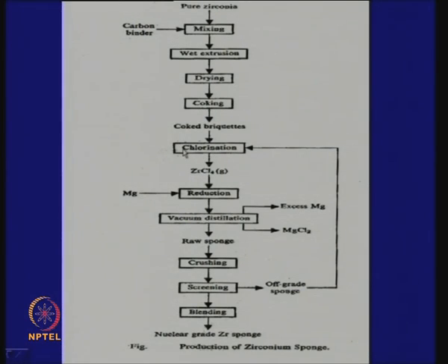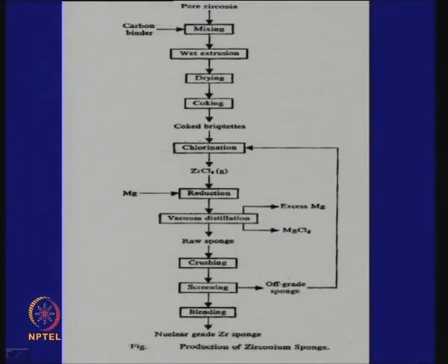zirconia ZrO2 plus carbon, it will now be chlorinated. So, it is chlorinated in presence of carbon. Zirconium oxide, as I have mentioned, is too stable an oxide; without carbon it cannot be chlorinated. In presence of carbon it will be chlorinated. We will find this carbon is coming from recirculation. We produce zirconium tetrachloride gas, it will be reduced by magnesium in the gas phase.